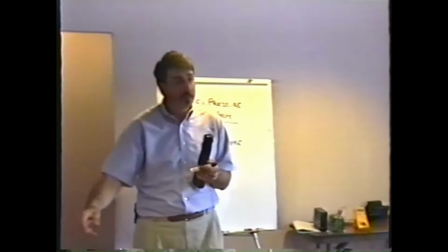10 ohms is correct. Let's see why. This is a tricky thing, but there's a reason why I point this out to you. Okay, brown is 1. We got that. That's easy. Black is 0. Okay, the third band is telling you the number of zeros to put after the first 2. How many? Zeros.